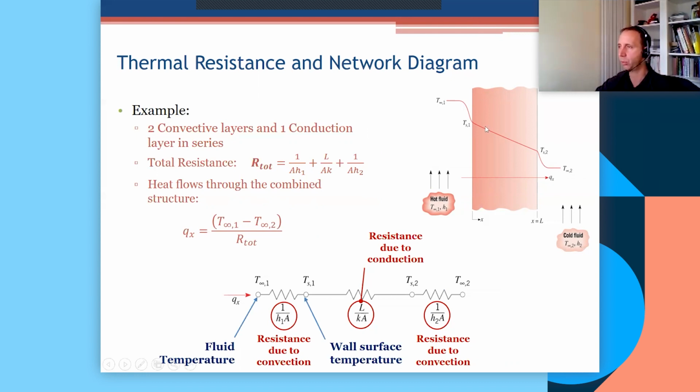Okay, so let's not go into the details, but we know that the red curve here represents the variation in temperature as you progress along a line perpendicular to the wall. No matter which line you pick, as long as it's perpendicular to the wall, you'll get the exact same temperature profile if you were right about your assumption that you have a one-dimensional heat transfer problem.